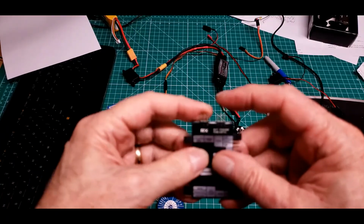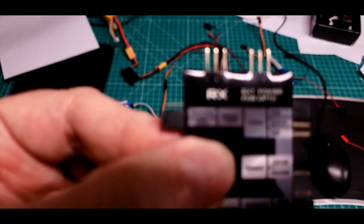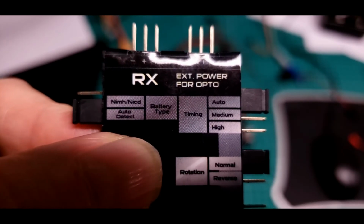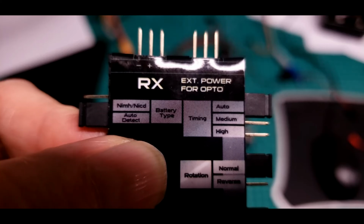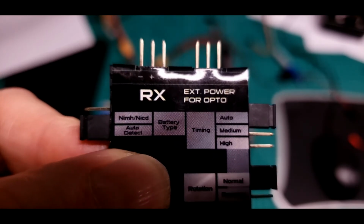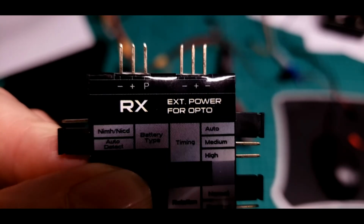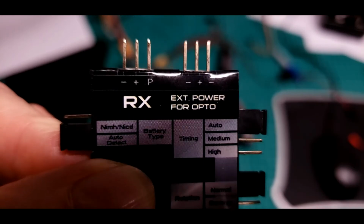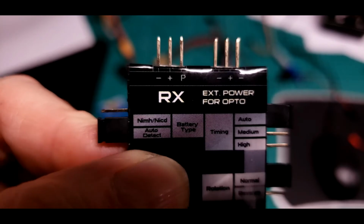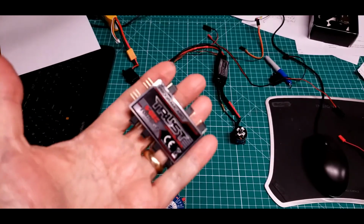You would plug the ESC into the right port on this device, and you would plug your RC receiver into the port on the left side that would supply your pulse width. So you could do the high throttle to put your ESC into program mode, and then everything in this card would be programmed into your ESC.